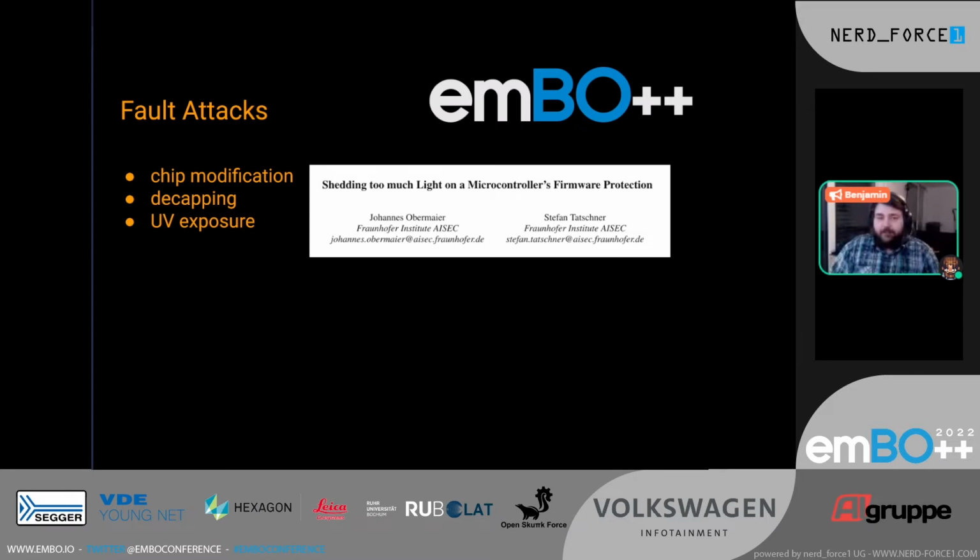And they did this because when you study its debug protection, it has 3 states. It has no debug protection, meaning no security, you can access everything. It has medium debug protection, which in this case means you can only access RAM and registers, which is quite similar to what we saw last year on the Nordic NRF51.